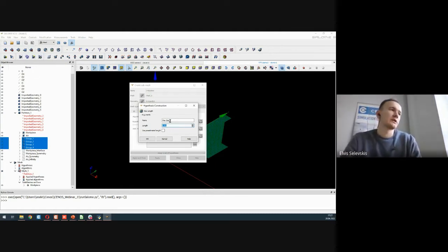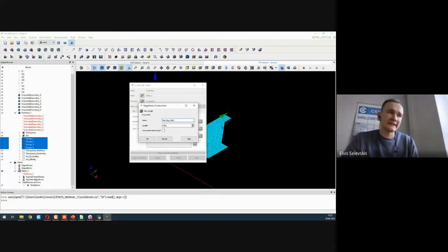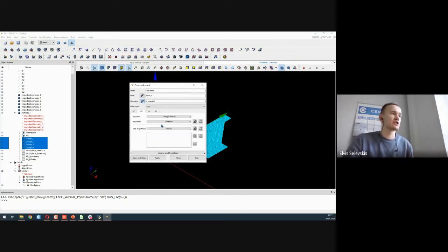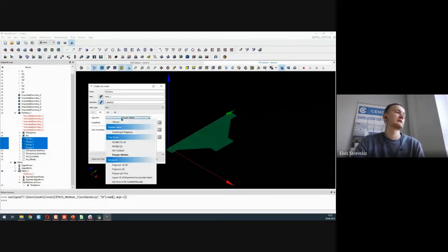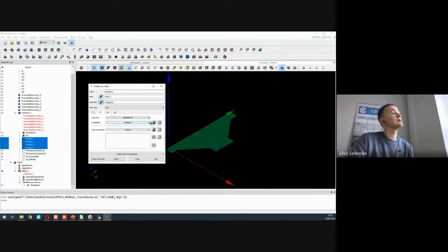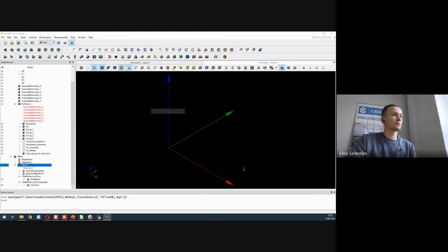One quick tip which I can tell you, which we have seen, if you are interested more in the workpiece heating, you can go quite rough with the inductors mesh. The results shouldn't change too much, even if your inductor is quite a bit rougher than the workpiece. Once again, of course, we select the algorithm to be again 2D and hypothesis to be length from edges. Yeah, press apply and close, clearing up the mesh data once again, and computing the mesh.